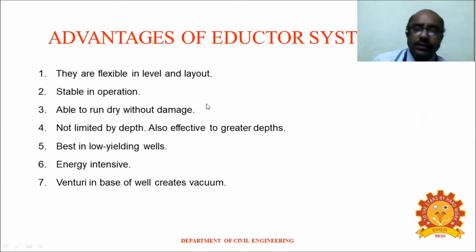In some other cases, if the water is not there and the pump is running dry, it causes damage, whereas here it is not so. It is not limited by depth, so it is very effective to a great depth, and it is best in low yielding wells. That is, when the soil is fine grained, the yield will be less.